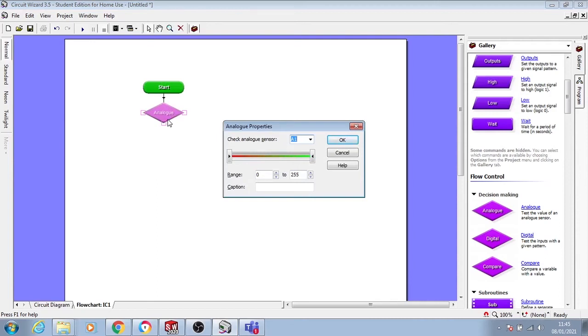You'll quite often see that in electronics. And what that's done is split that 0 to 5 volts into the range of the digital range. So in this case, however many bits it is, it's 256 steps. So it will measure that 0 to 5 volts in that range, and you can calibrate the range here. So when it's within that range, you can say switch the street lights on or whatever. Play around with it, have a little go yourself.